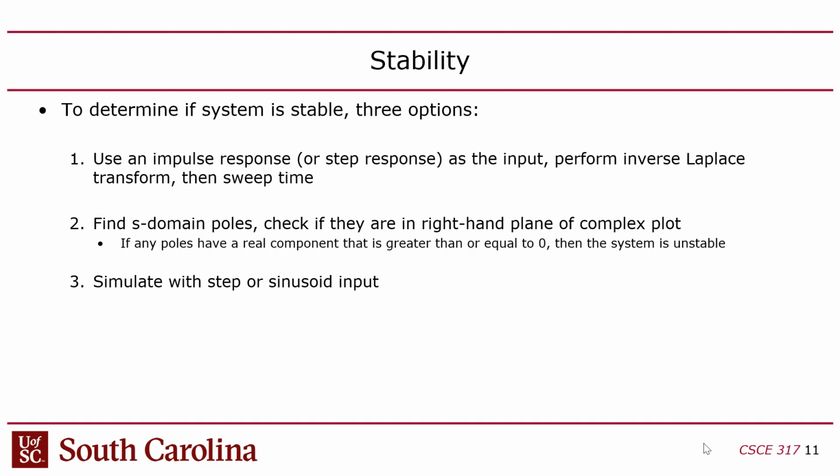And this is kind of a fundamental question. There's three ways that you can test it. You can hit it with an impulse response as the input and see what happens. The second thing you can do is you can find the S-domain poles, and the third way is you can just simulate it. You can just run a simulation.